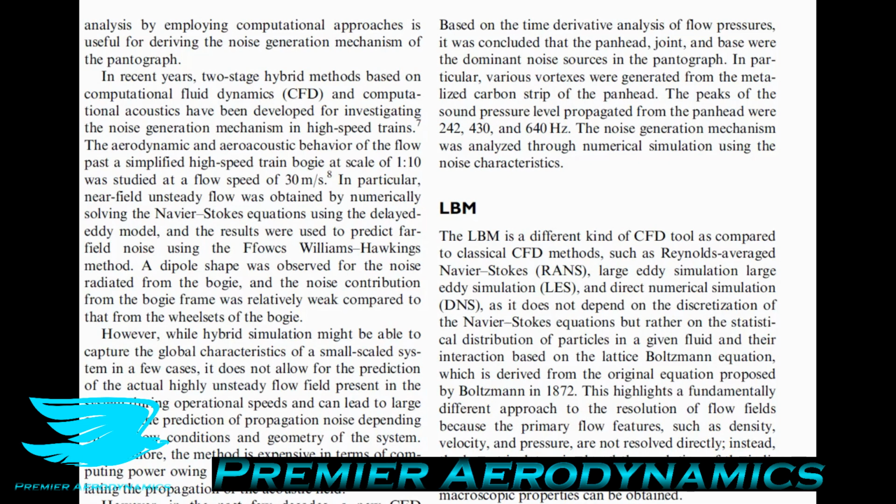So why is that? Well, in this particular case, they're looking at DES, and DES is a combination of LES and RANS. So how DES works is that depending on where you are in your simulation, you're going to be triggering either LES or RANS equations. In effect, when you're close to the wall, you're going to be triggering the RANS equations. So that's problematic because that's where a lot of the sound is being produced. So if you're using turbulence modeling, you're losing a lot of information, or you're not even getting the information to begin with from the RANS equations. So that's why DES can struggle in this particular case.